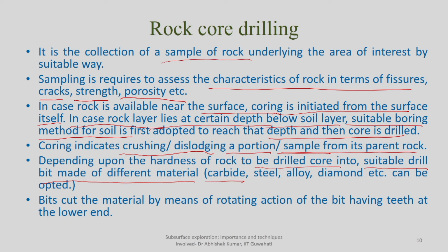Depending upon the strength or hardness of the rock available, you can go with carbide, steel, or alloy, or even diamond bits. Of course, as the name suggests, diamond is very costly, but you can use it in very hard media like granite, where other drill bits may not work, for collecting the sample or for coring it. Bits cut the material by means of rotating action.